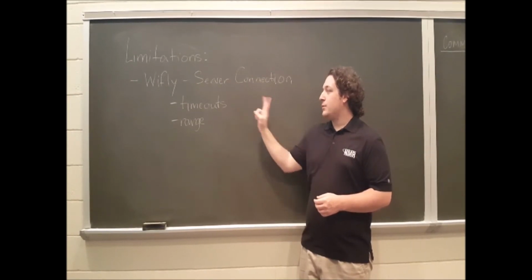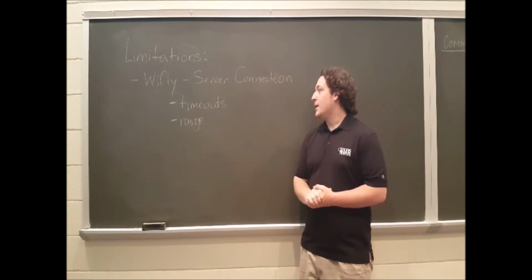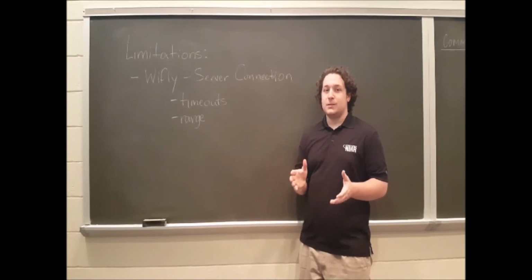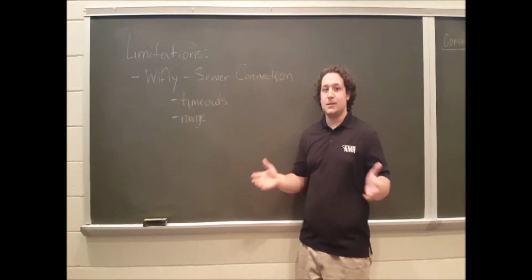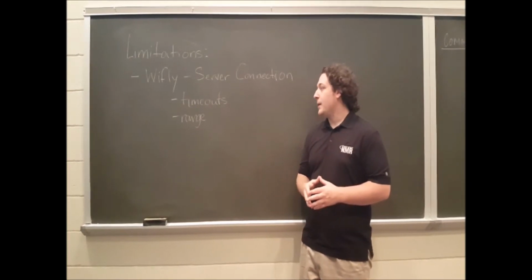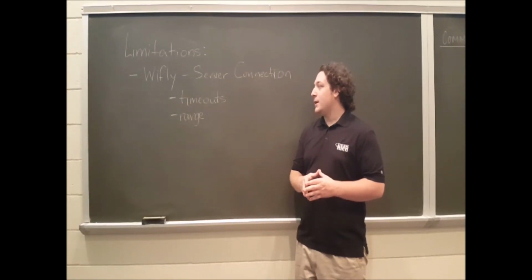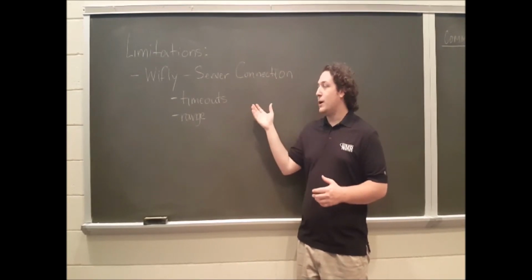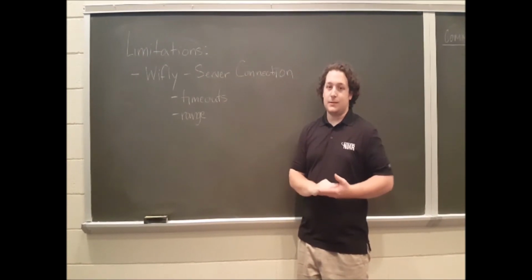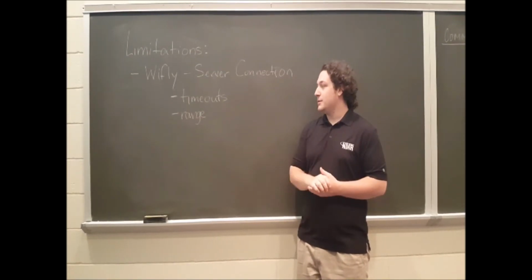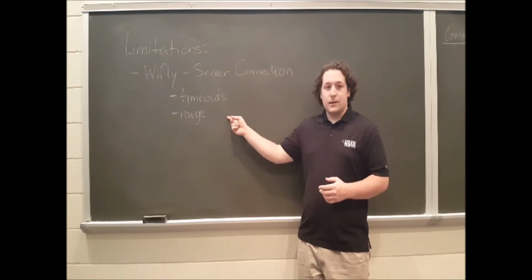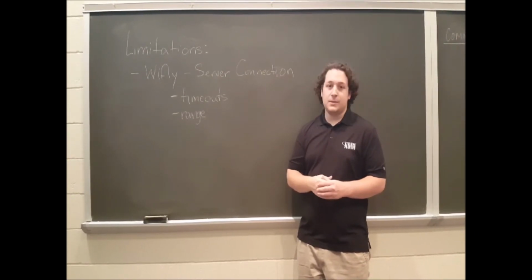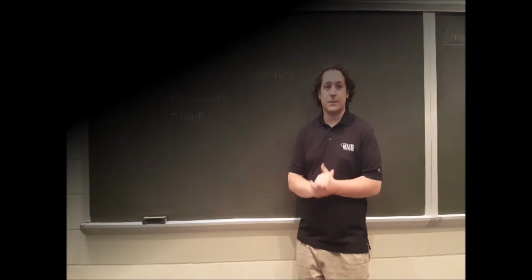We fix that with two parts. One is from the rover that will occasionally send out a heartbeat message that's otherwise useless but just sends some type of communication to the server. And the other one is a reconnection state in the back end of the server. Once the Wi-Fi is disconnected, it will try to reconnect by sending another useless message. Otherwise, we had no range issues, we had no message dropping issues, it worked flawlessly.